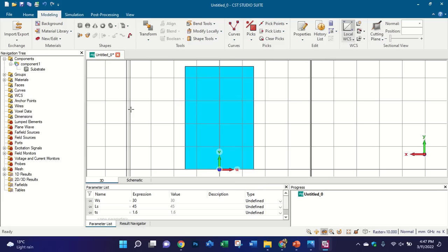What do you think if we can use SIW based reconfigurability? Actually, in an SIW based reconfigurable antenna there may be some issue in using the PIN diodes. It may be an issue because in SIW you integrate the shorting pins that connect your patch and the ground plane. If you are connecting the PIN diodes on the patch, on the radiator, on the SIW, then surely every portion will be grounded. So in that case maybe PIN diodes will not work very well, but you need to check it first.